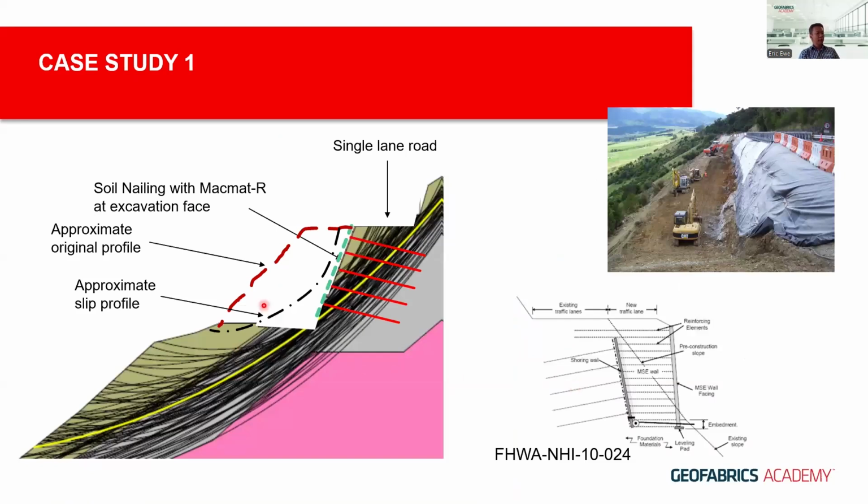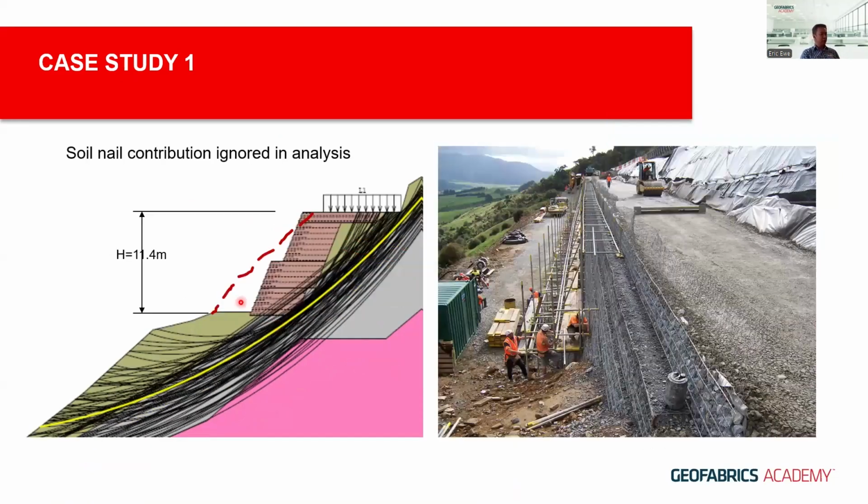So this is what I mean. Excavation, first stage, lay the surface with temporary nails, by the way. These nails are ignored in the long term, so non-galvanized. To ensure the single lane, excavate down to the intended founding level, okay? And then build a reinforced soil structure, in this particular case with a Green Terramesh unit with rock fill front face, layer by layer, up to the final finish level.